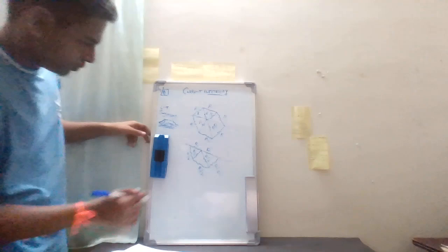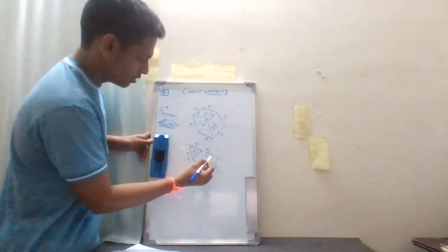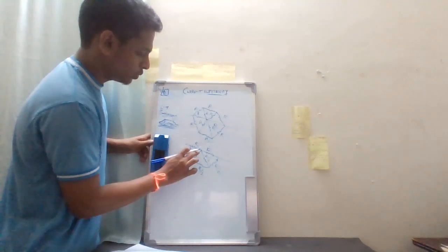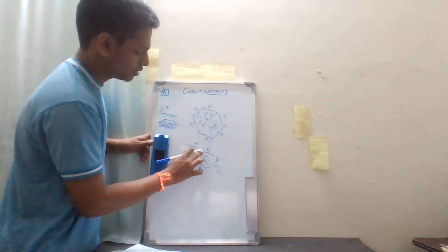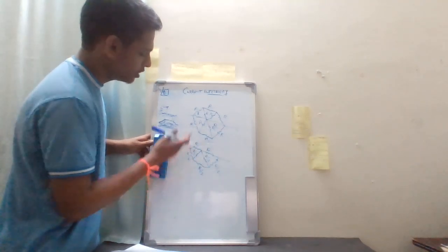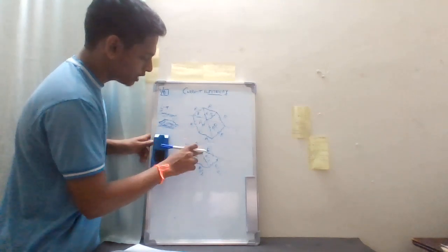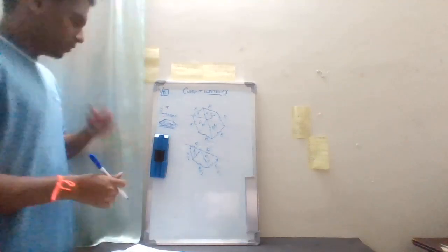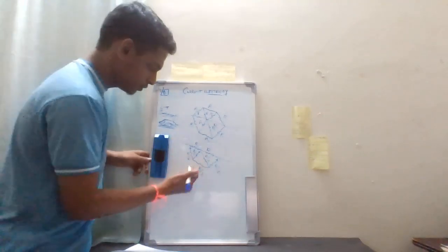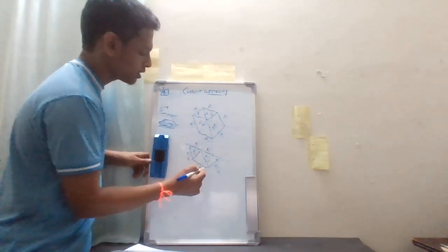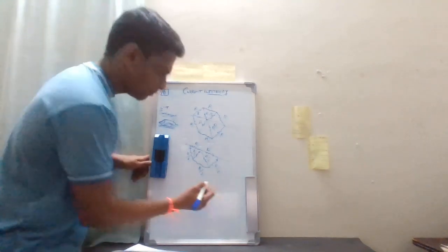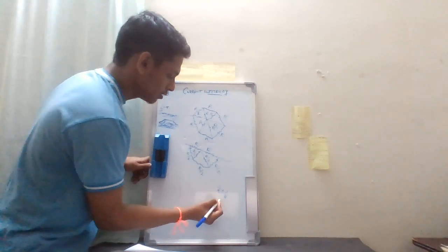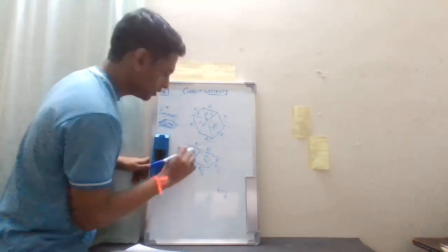But if we see through symmetry, current which goes here is joining here. So it won't take any deviations. So it won't go like this or like this. So no current will be passing like this. But we can assume it would be going like this. So if we join like this also, there's no problem. So this would be R plus R by 2. That would be 1 by R plus 2 by R. Yeah, so R by 3.